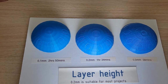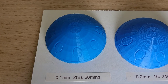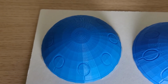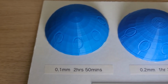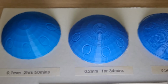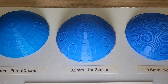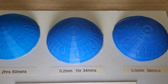So let's start with a fine setting. This is 0.1 millimeters. If I can zoom in there, you can see that's quite fine layers. But from the top, there's a few steps you can see. Now that particular print has taken 2 hours 15 minutes, and we go to a 0.2 millimeter setting. You can start to see some of those lines are a bit more prominent there, and that's 1 hour 34.